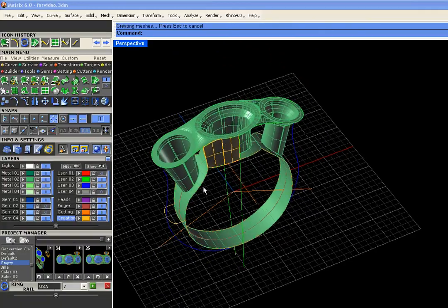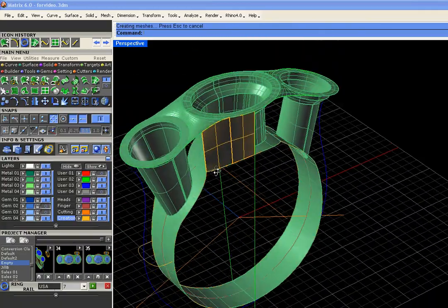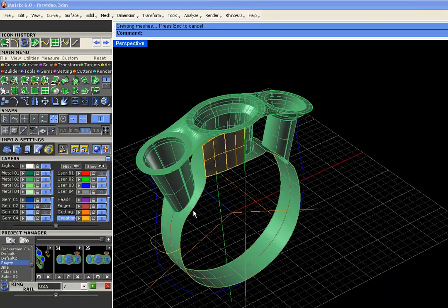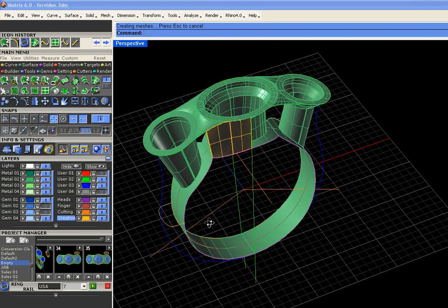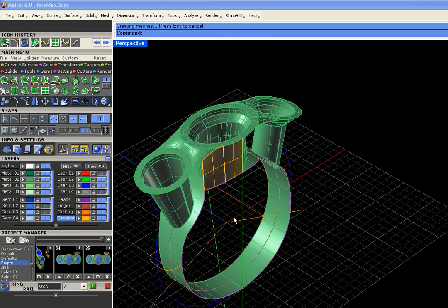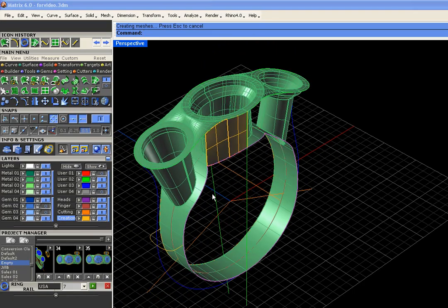Now let's see if that'll be enough to patch. Okay, so for patch we want single curves that stop and end where all their little patch friends stop and end. Otherwise your patch will go really wonky. So let's split this curve with this curve. There's one of them. This guy has to be split in half again with his neighbor. Then we have this guy. He also needs to be split with his neighbor.